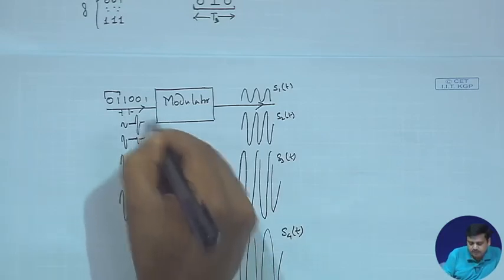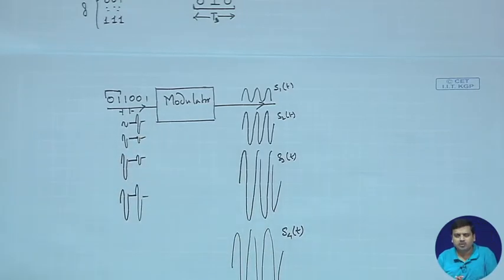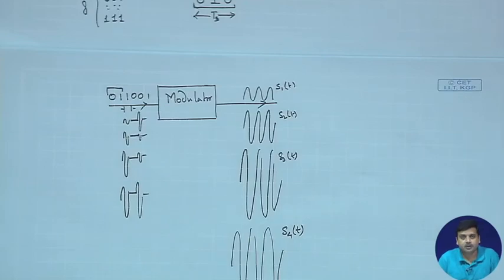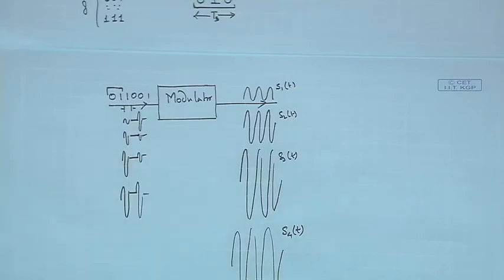Again I would be sending nothing. This is a bit awkward from multiple points of view. One particular modulation scheme could be that the first waveform has an amplitude of 0 and the second waveform has an amplitude which is non-zero, which is also known as on-off keying, a special case of what we are dealing with here. In that case, when you are not sending anything, that could account for certain information being sent. So, generally we would not do a situation like this.